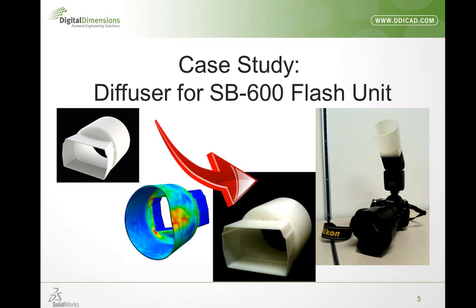We're also going to assume that my heat power lasts about a tenth of a second for each flash cycle. So we're going to model one cycle, one flash, for 2 seconds. Upon 2 seconds, we're going to flash it once and see what our temperature distribution looks like on this model.